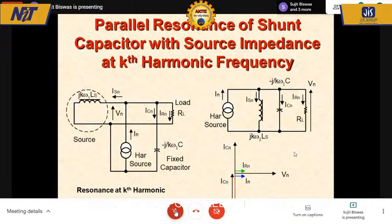So we have to be very, very careful on a distributed generation system where we are going to have a lot of harmonics injected into the line at different frequencies, because we have different switching frequencies and different topologies of converters. We have to be very cautious in the application of any types of capacitors or filters onto the line. Otherwise, we land up with more problems created by us than there were before.